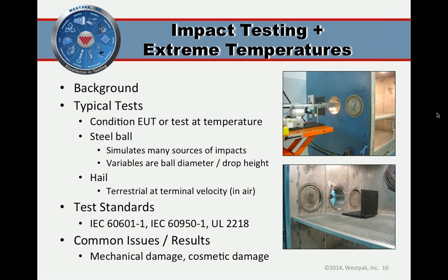So impact testing like this at temperature extremes is a concept that's been around a long time, not just for catchers, but for product reliability as well. And certain products, just like me, have very different characteristics in cold versus hot environments. Extreme cold tends to cause a brittle-natured failure, as Mike mentioned, in thermoplastics and similar materials. Hot environments can cause a large increase in the level of plasticity, maybe even in me, I'm not sure, especially with olefin foams and cross-linked polymers. So temperature extremes and impacts is something that's been around for a long time. Mike, how about drop testing?